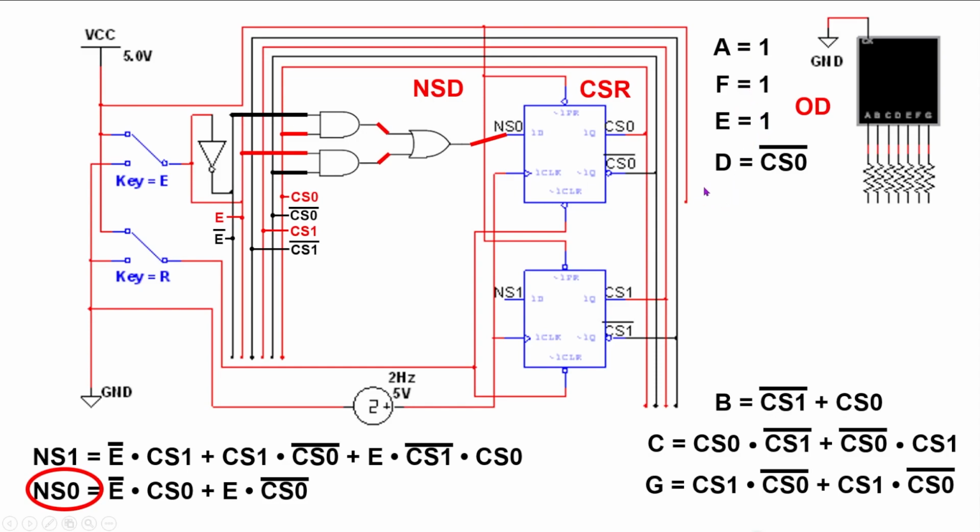So they made an extra wire that follows the wire below it here, not realizing that they were just being redundant, and they plugged it into the VCC. Well, that's what this wire is. This signal plugs into a 1. The VCC voltage, 5 volts, that's a 1. So you don't have to plug into this wire 3 times. You can take one wire over here and plug in A and E and F, and you've got all 3